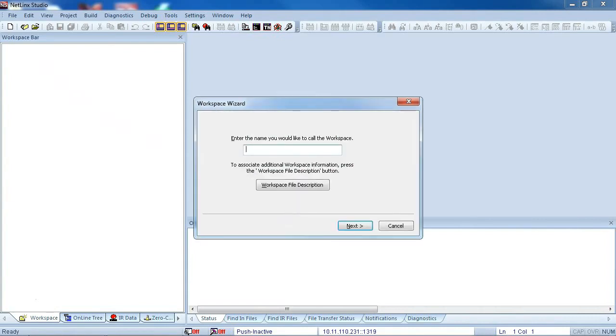The first required field is the name you want to assign to the workspace. Consequently, this will become the file name Studio uses to generate the .apw file, which, as we just learned, is essentially the framework which contains the names of all the projects and systems within the workspace, as well as links to all of the files that are part of the workspace. I'll name this workspace ABCU_campus.